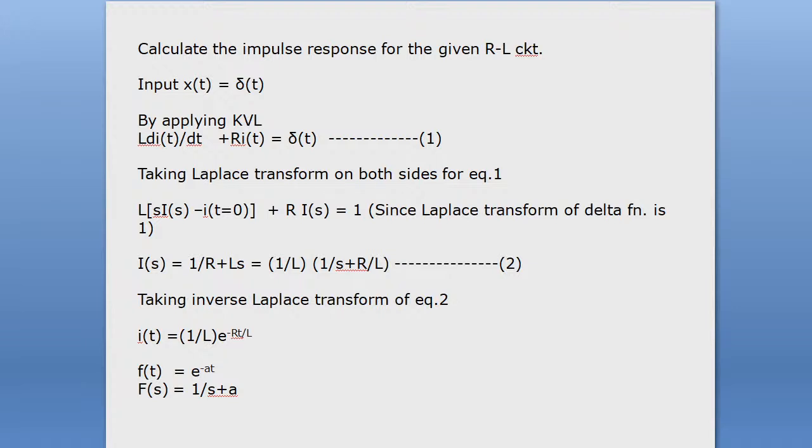Whatever step response you obtain, you just take the derivative of that response, and you will get the impulse response without further calculation for impulse input. And vice versa.